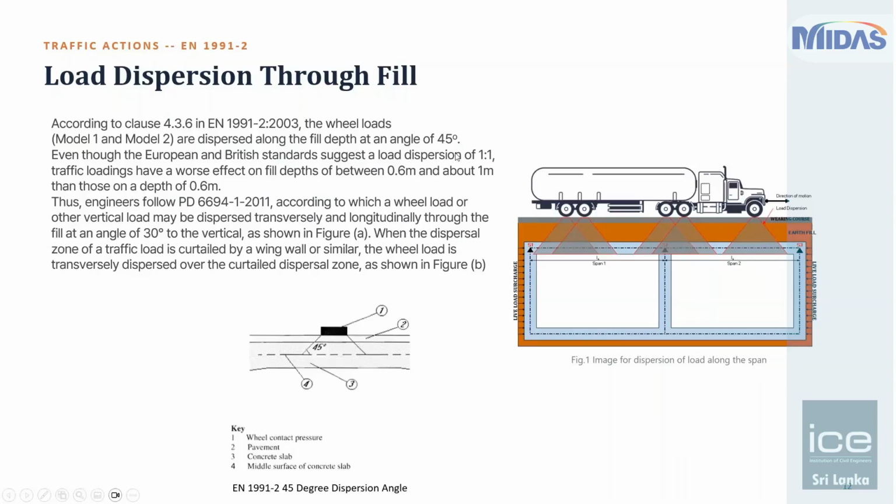Okay. Now, say if you have a pavement thickness of say 65 thickness, and you have a slab depth of 450 thick. So at the center of the slab is where we would estimate the pressure loads from these tires. Say you have 150 kilonewton of a tire load divided by 0.4 times 0.4, that is your tire pressure at the top of this pavement, which is 937.5 kilonewton per meter square of patch load in 0.4 by 0.4 meters.